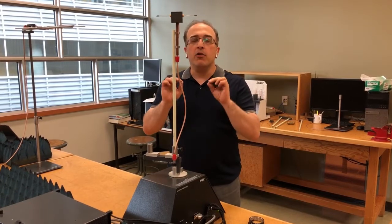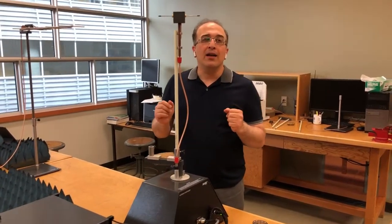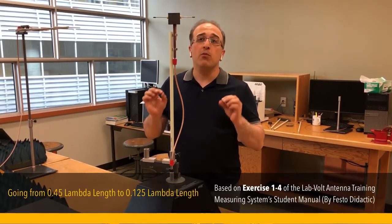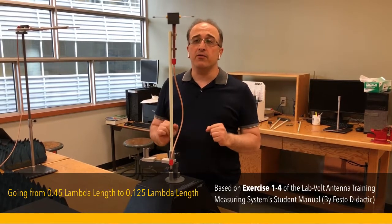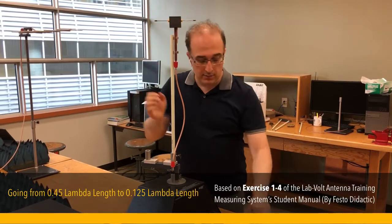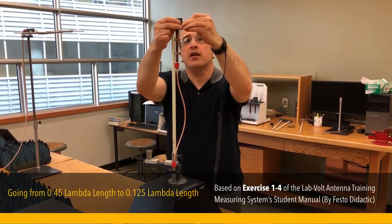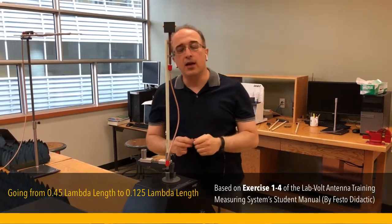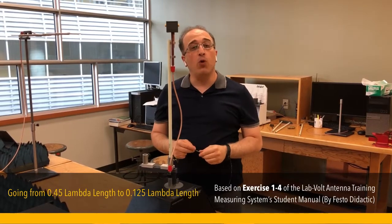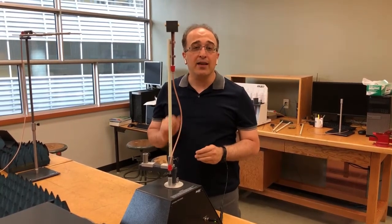But we want to go much smaller than that. We want to get to around a lambda divided by 10 dipole antenna, or to be precise, 0.125. To do that, I'm going to remove these two arms. And what remains inside this dipole now has a total length of 0.125, so it's about a lambda divided by 10 dipole.